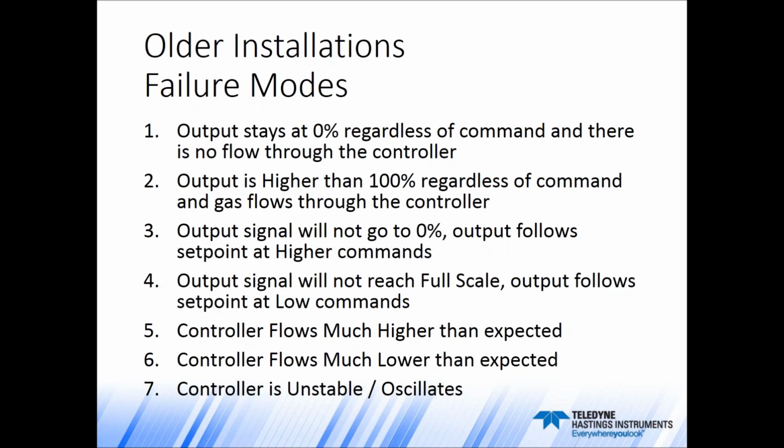Output signal will not go to zero, and output follows set point at higher commands, but not at the very low set point command. Output signal will not reach full scale, but output will follow set point at the low commands. Controller flow is much higher than expected or much lower than expected. And finally, a thing that has troubled us all in the MFC world, controller has become unstable or oscillates.